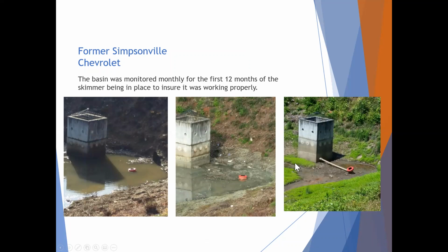6 feet below what is now the bottom of the basin is a 2-inch orifice that had obviously gotten clogged and had caused 6 feet of muck and debris to accumulate in this pond over however many years it had been. So this was going to be extraordinarily expensive to fix. Like I said, the pond had severe slopes. They were going to have to cut in a road just to get down to it and muck it out.